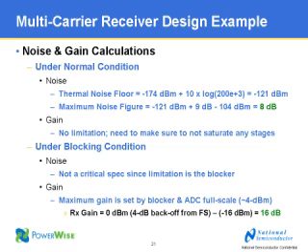We start from the basic thermal noise in that bandwidth of 200 kilohertz, which is about minus 121 dBm. As Scott highlighted, we need to be able to resolve a signal as low as minus 104 dBm. That means that if we have any rise in the noise floor beyond 8 dB, we will not have the adequate carrier to noise plus interference ratio of 9 dB. So if you go from minus 121 plus 8 dB of noise figure, you get to minus 113, and that's the limit, because 9 dB above that is minus 104. So what you want to take away is that a noise figure of 8 dB is what you need for that receiver.